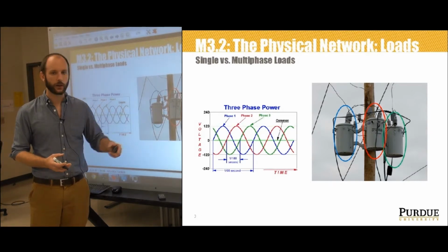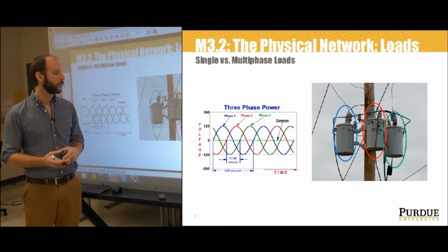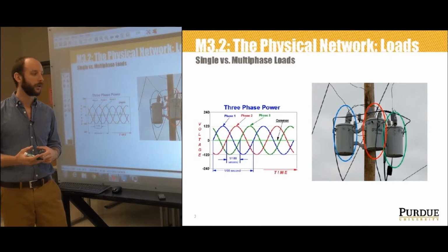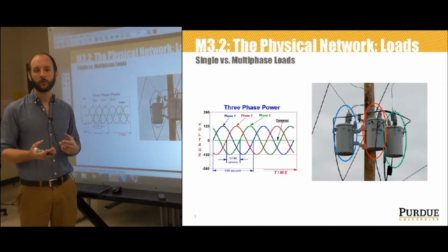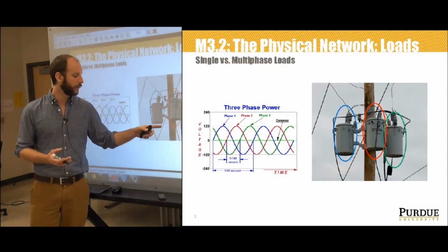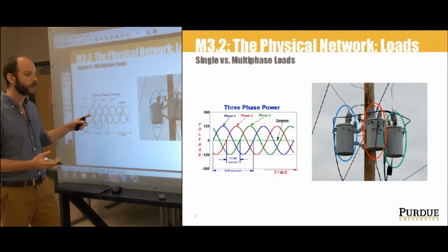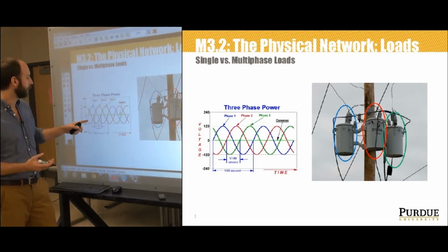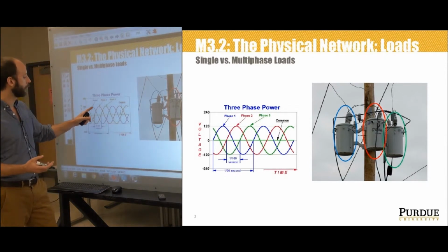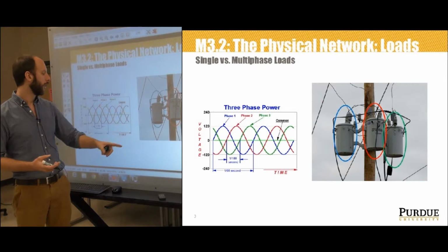Each of these transformers on this utility pole is connected to a different phase of the generation supply, and therefore the voltage current relationships in these transformers, which I've highlighted in different colors, blue, red, and green, are going to be represented by the phase diagram shown here. Arbitrarily with this one, we're taking blue as the reference phase.